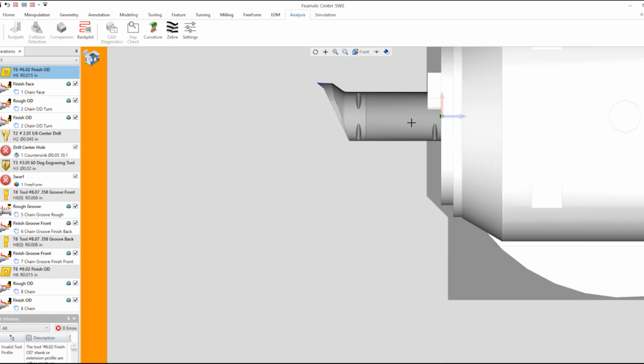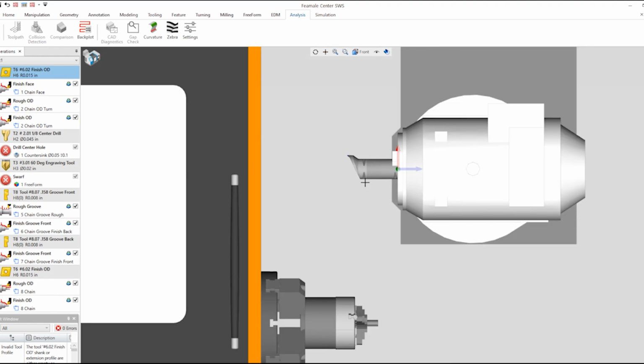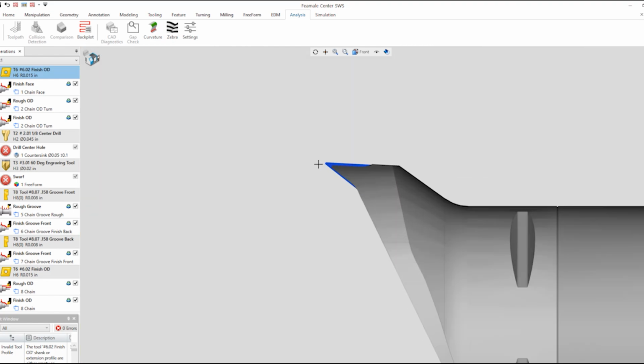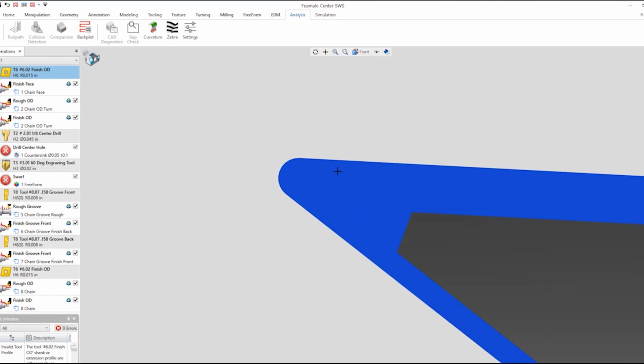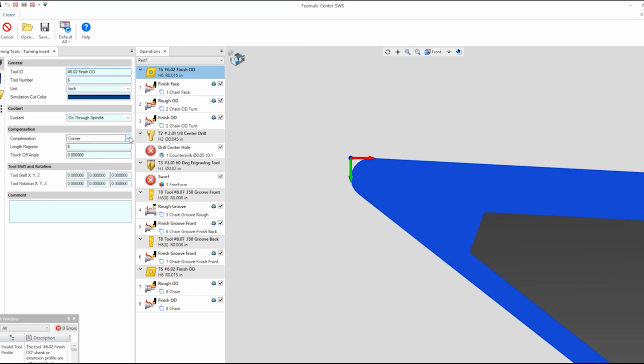Look at it here. Now, on the Mazak, it comes in this horizontal direction, but it's going to index the B-axis 90 degrees to actually do the turning in this case. But let's just zoom way in on the tip radius of the tool, and let me open the tool up again. Now see, that's set on the corner. You can see, the red arrow is the X, and it's pointing upward because the tool runs with its 90 degrees index down. In this case that is why it looks that way.